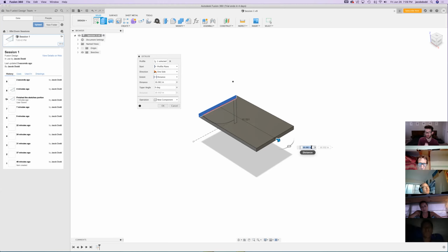Because doing so means that we're able to change it later on a lot easier than if we were to use a fixed value here. But you could. Absolutely, you could have just overridden it, because you said, okay, I don't want the shelf 3 feet long, I want it 2 feet. But in using the parameter, we can change that in one central location, and you'll see how that's beneficial. I was just wondering if I was seeing what I thought I was seeing.